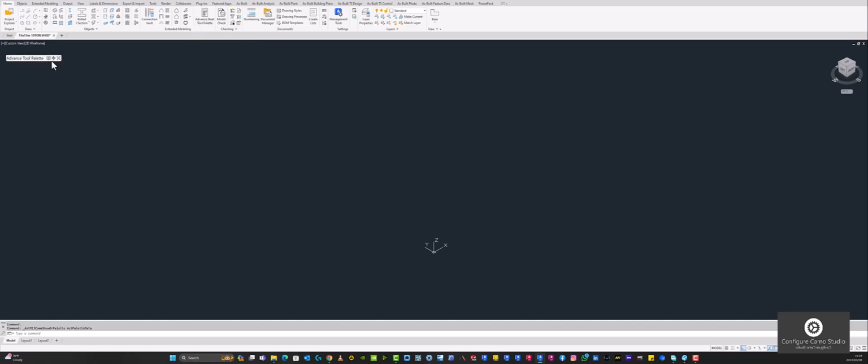So in order to see the options that you've got under this tool palette, you just click the plus sign, which is like your drop down arrow. You'll see that you've got all these options. They are categorized by usage. So you've got your move, copy, mirror. You've got a lot of options that you can use during the project. UCS, and how to highlight things that are assembled or bolted or welded in the workshop, and things that are bolted or welded on site. This is where you can highlight them as well. So it's got a lot of tools to use.